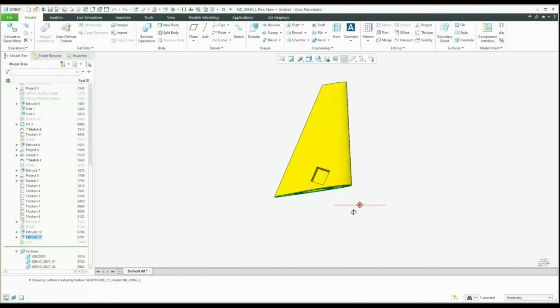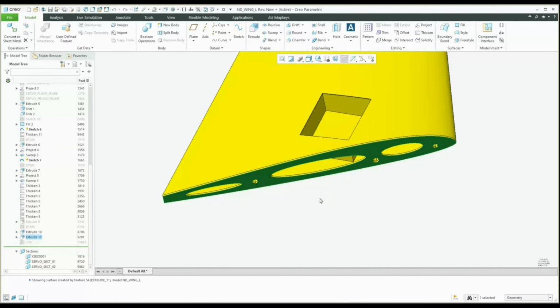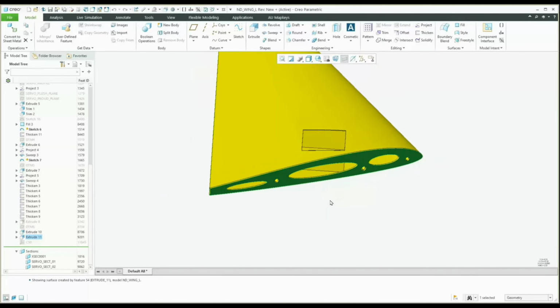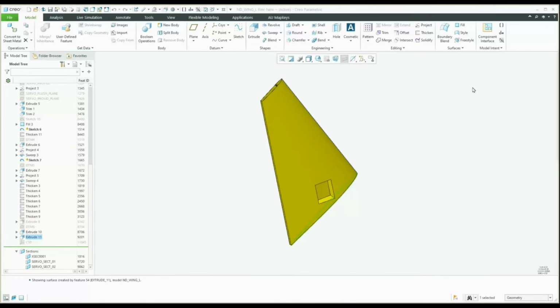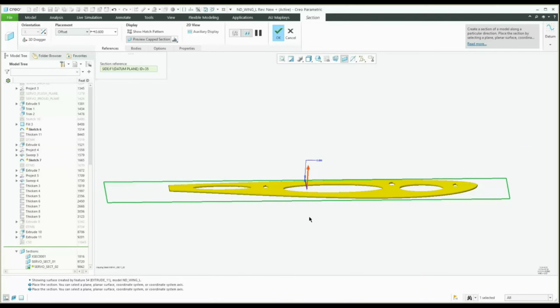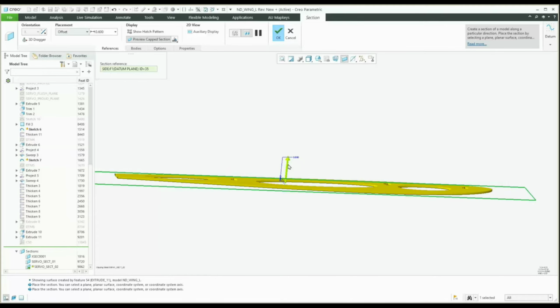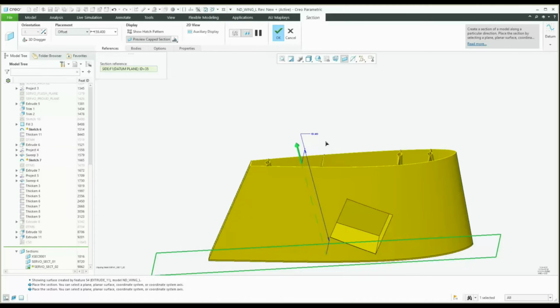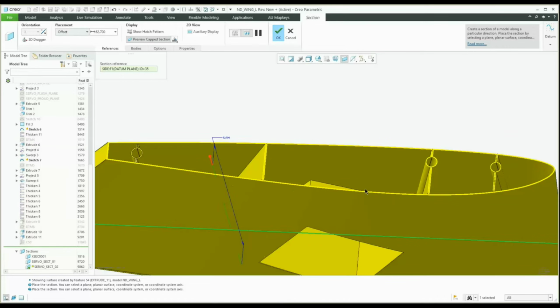I have designed this part to be printed with the root of the wing as the first layer on the print bed. I can actually specify an initial length to print as solid, rather than spiral vase, for the first few layers. This gives me the benefit that I can design a single rib at this root section of the wing. This rib will make this section stiffer, but will also make a convenient surface to glue the wing to the fuselage. As we progress towards the tip of the wing, you can see how I have designed stiffening features that still obey the rules of spiral vase printing.